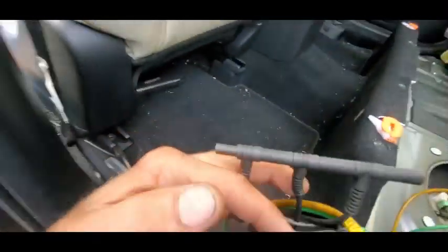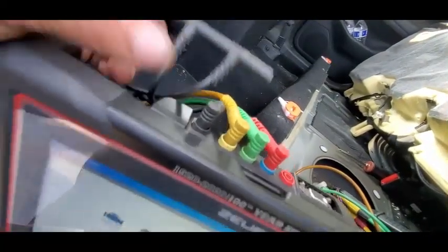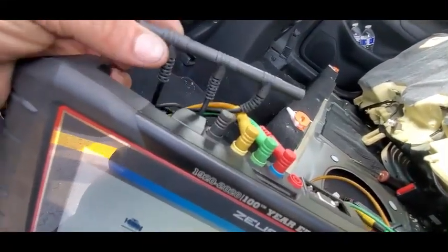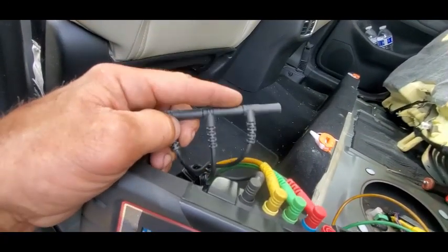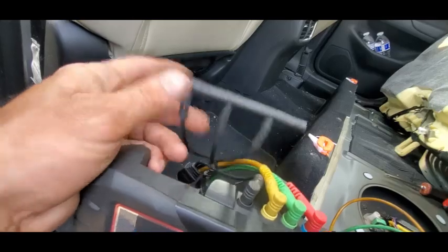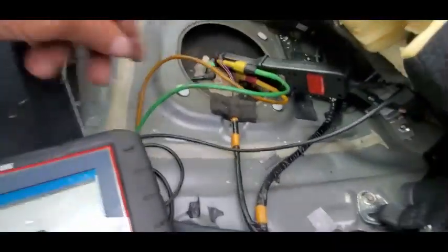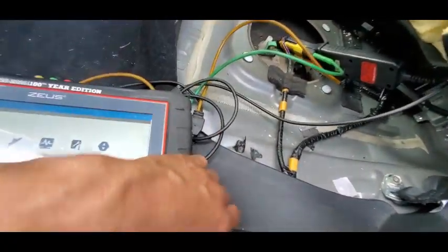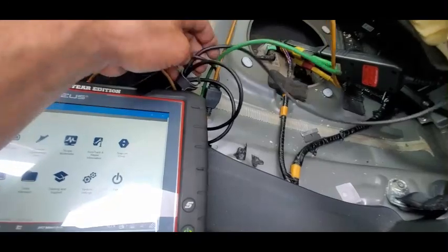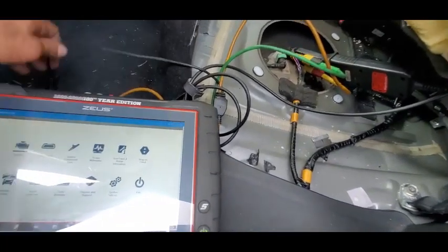So all our grounds are stacked, okay? We don't put them in there like this. We use that extra one on the yellow and we stack them like this, okay? So we've got our amp clamp, green trace, yellow trace, all stacked. And then it comes in on the yellow there for our ground. For our other side on the yellow, because Snap-on scopes, you only need to ground your yellow and your green, right? Because the other two are already grounded internal to the scope.